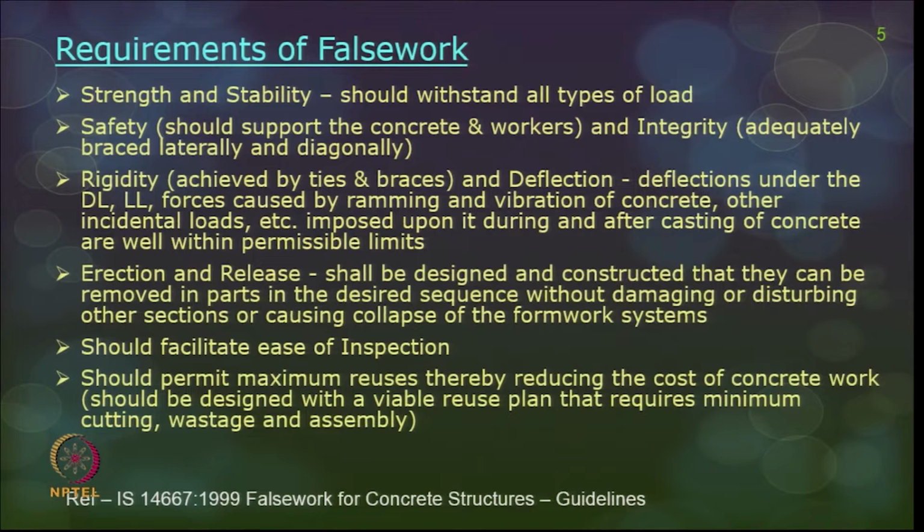There can be a lot of deflections which happen because of the dead load coming onto the formwork, then the load of the fresh concrete, live load because of movement of workers and equipment, and also forces caused by pumping of concrete or vibration of concrete as a result of compaction. So, all these should be taken into account. The formwork should be very rigid and stable.